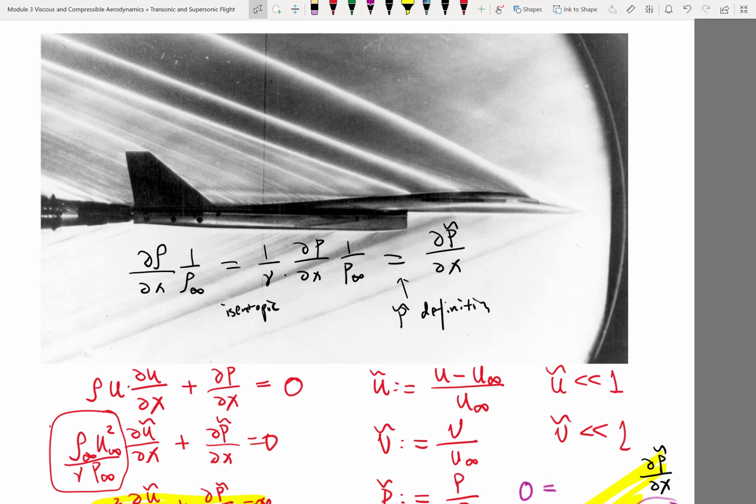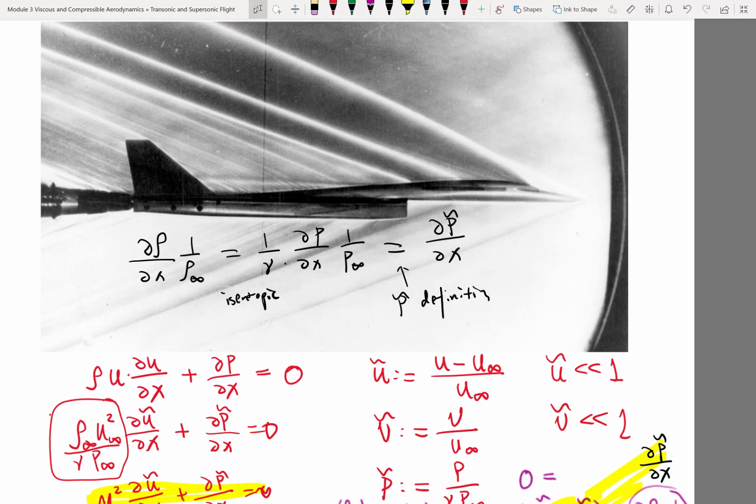But the difference is that instead of propagating in time, this set of equations propagates in the direction of the free stream. If you have a cross-section of air that's staying with the ground, and you have an airplane that flies through it, you're going to see the waves of velocity and pressure propagate on this cross-section, just like when you throw a stone into a pond.